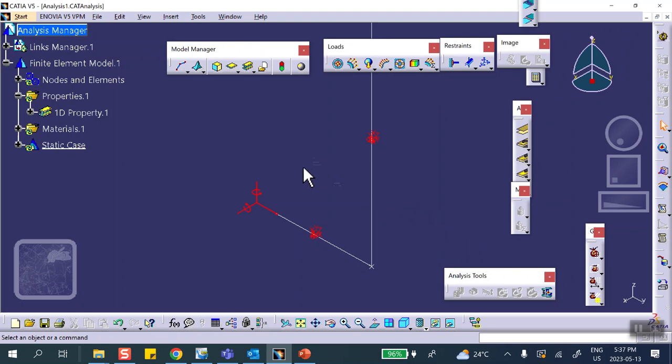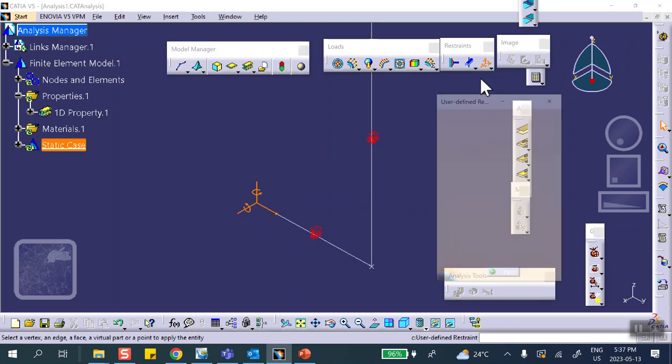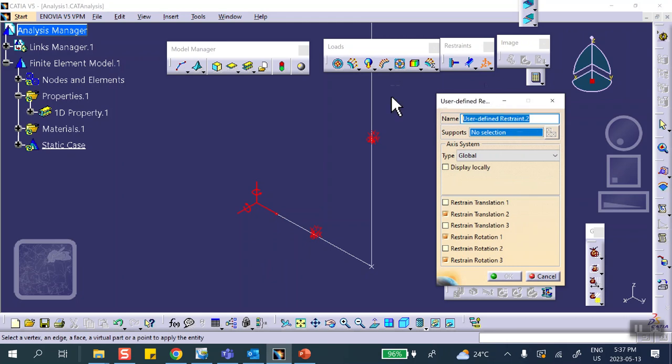Okay, good. Then I want to take that point and move it down. So I'm going to click on it, and I'm going to call it pushing down, 0 in the direction Z, because I want to be able to change that. And that is the point, right? Good.